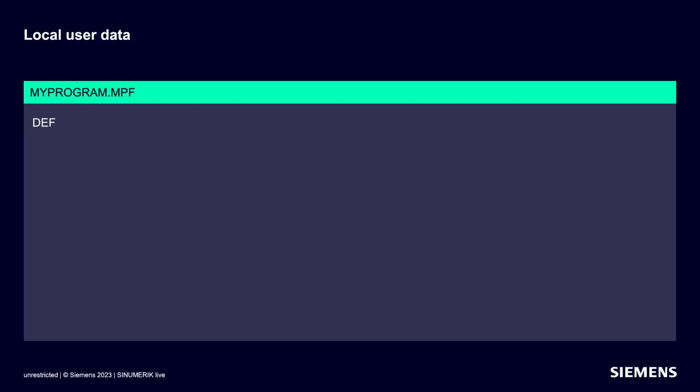The def command is immediately followed by the data type for the desired variable, in our case, an integer, followed by the name of the variable, counter, in this case. Please always be careful when assigning the name, because this name must not be the same as the CNC commands, system variables, or variables of the machine manufacturers. If there are any identical names, an error message will flag them up when the program is started.